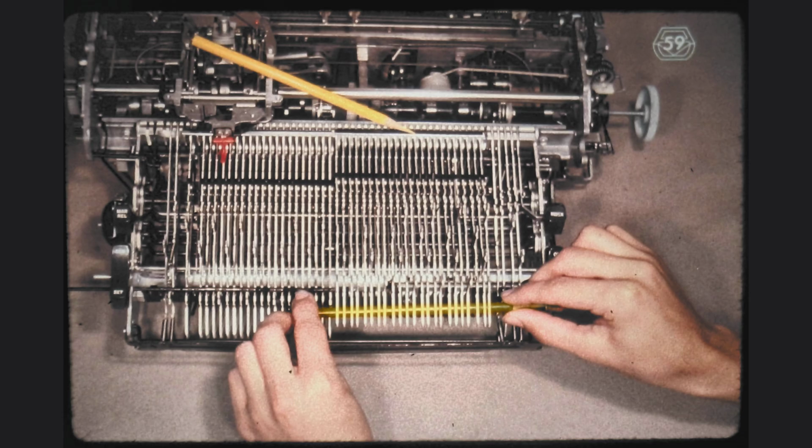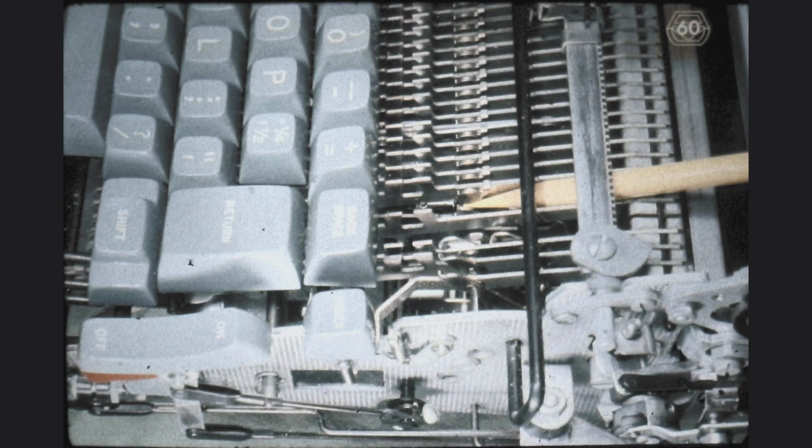You may need something a bit longer, a long screwdriver perhaps, in order to simultaneously lift up all of the keylevers on your typewriter. None of this is needed, of course, if your typewriter has the old-style keylever pawl restoring springs. Go ahead and butterfly the keylevers on your machine now.